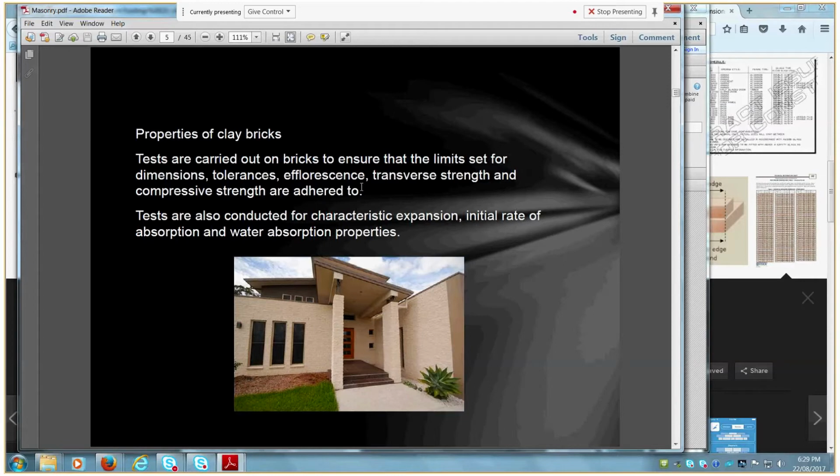It's different from salt damp. Same sort of process, but salt damp is where you've got an ongoing problem of efflorescence where it continuously wicks moisture and you get depositing of salts on the surface of masonry or concrete, and the salt deposits start forming crystals and wedging out little bits of sand or stone.